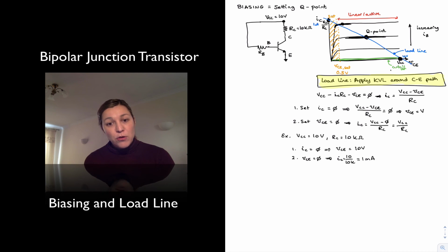One of the things that we're going to focus on when we design a biasing configuration, a biasing network, is stability of the biasing point. We don't want the quiescent point that we set, the nominal Q point, to vary depending on external circumstances. One of the key parameters that we're going to consider variations about is the beta of the transistor.